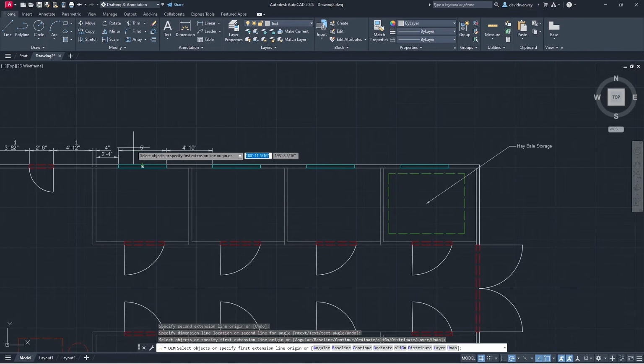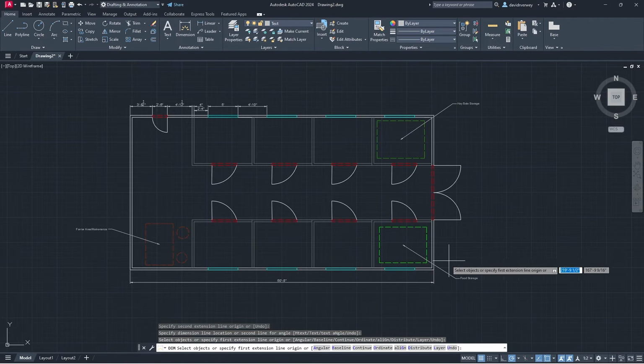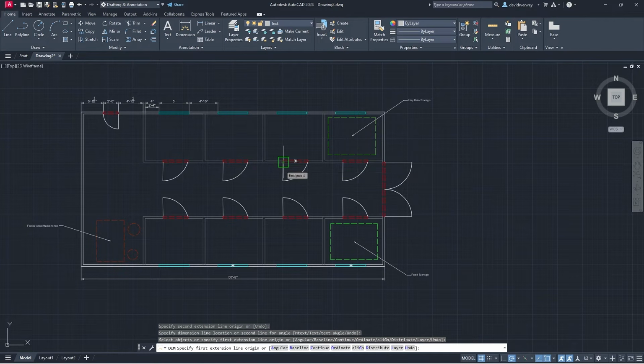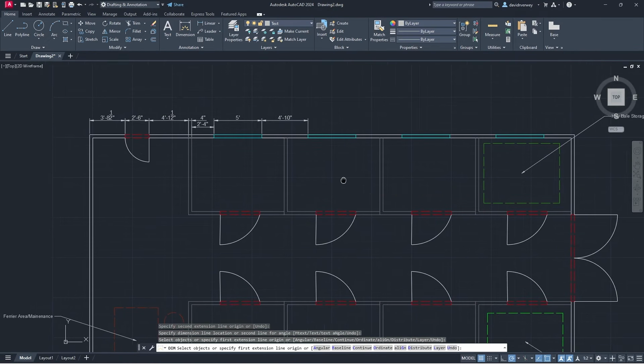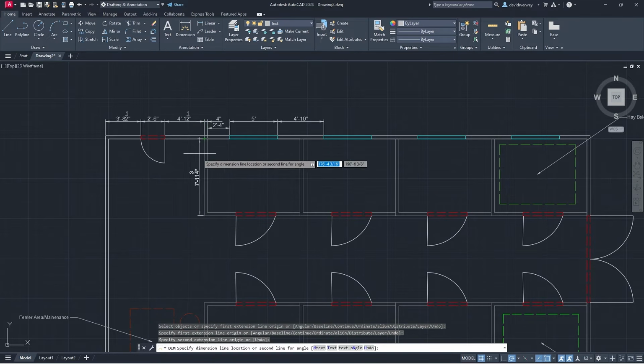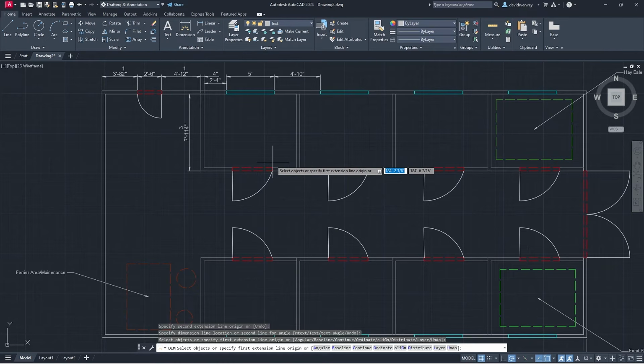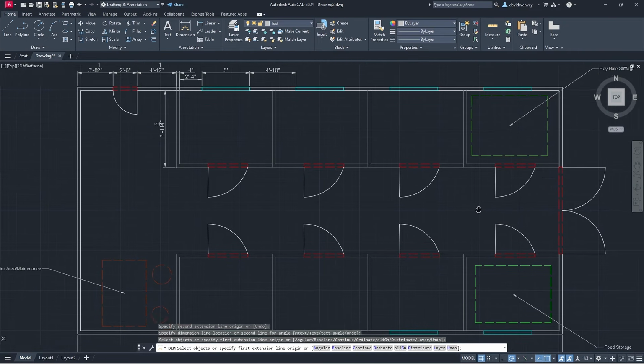So, because the window is measured here, this is measured here, so it's all going to be the same all the way across, and we don't have to do it on the other side because we're going to assume it's all symmetrical. So once that's done, we're going to measure from the bottom here to up here. So a good rule of thumb is to measure things that someone would have a hard time figuring out in the field. So, you don't want to give them drawings with just the big dimensions with no little dimensions, because you need to give them the smaller dimensions so they can do the math to figure out what the other smaller dimensions are. So here I'm going a little overboard just to show you.